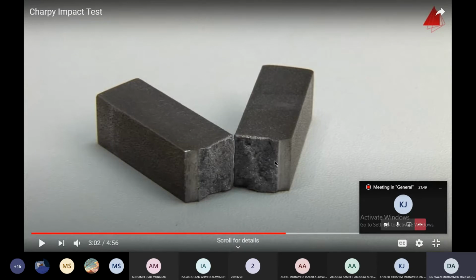The shape of the failure in the impact, when you have that side and you have a strained edge like that, and the failure occurs like a clear cut, which you can see here. This is an indication for a brittle failure. Like in the tensile testing, if you remember, we had a clear cut and we had what kind of failure there?